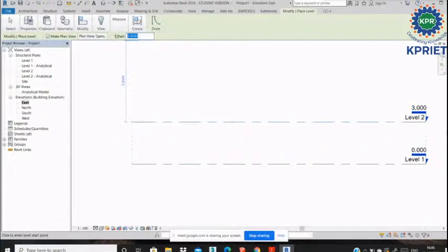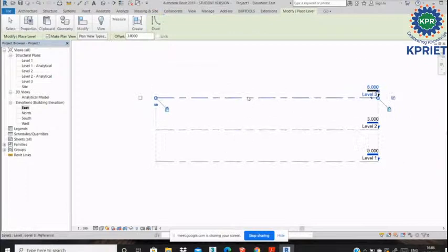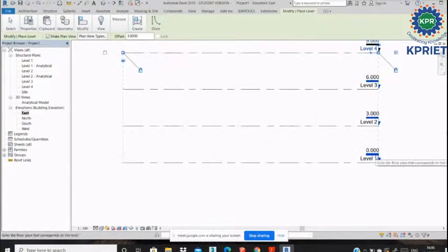So the opposite is there. I need a 3 meter, 10 feet is 3 meters, right? Enter the 3 meter, then go to draw, then pick lines, click this, right? Automatically it is at one floor, right? You simply created the level 1 as the ground floor.